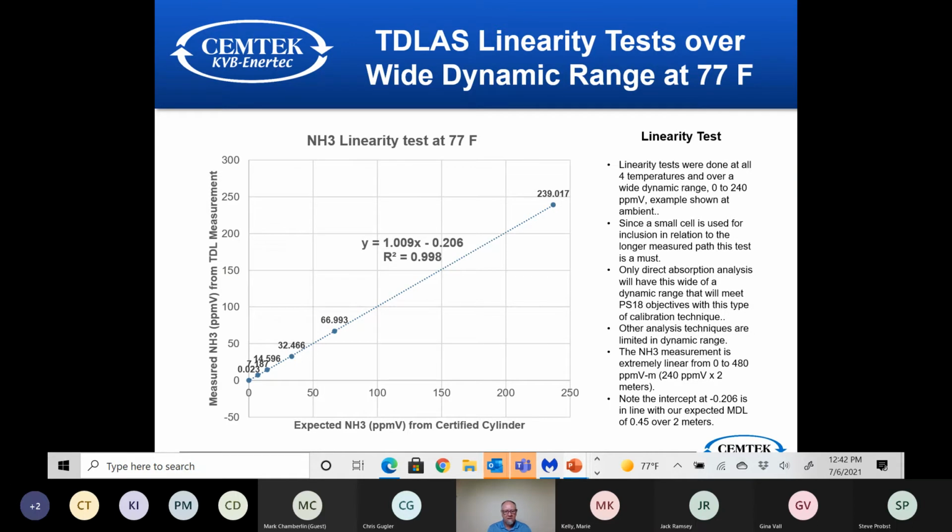So at that point, if the ammonia number changes, we're watching out for that, and we can say, okay, the process is down, you can ignore the number. But typically, even if you've over-injected your ammonia and saturated the SCR, and you shut down, and as you shut down, it's off-gassing that ammonia still, we're going to see that as it slips by, and we're going to measure it all the way down.